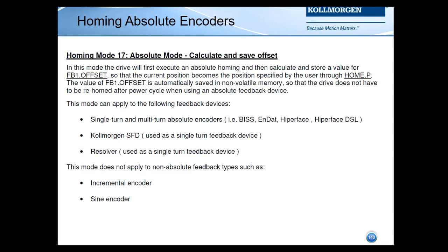This mode can apply to the following feedback devices: single-turn and multi-turn absolute encoders such as BiSS, EnDat, Hiperface, and Hiperface DSL, or the Kollmorgen Smart Feedback device, which is used as a single-turn feedback device, or a resolver, which also can be used as a single-turn feedback device. This mode does not apply to non-absolute feedback types such as an incremental encoder or a sine encoder.